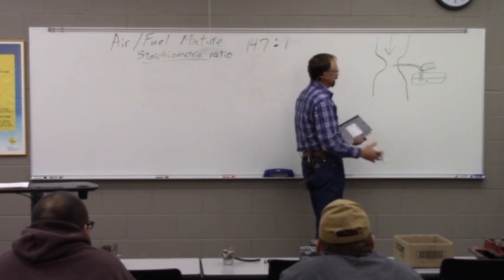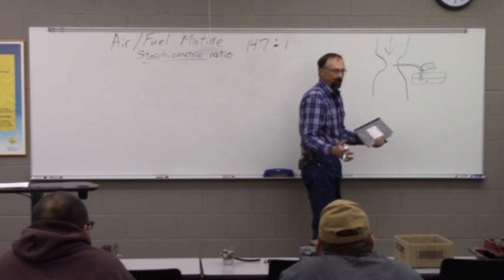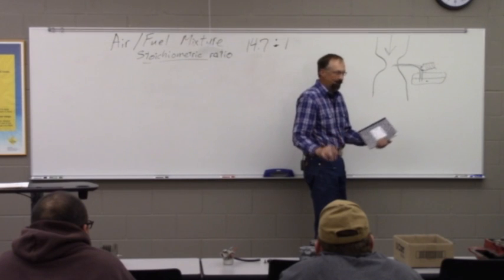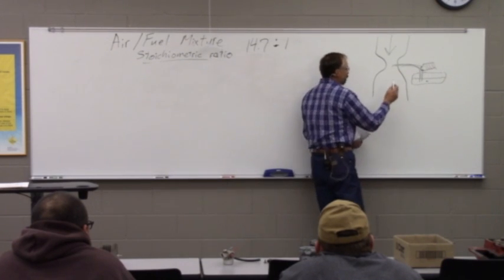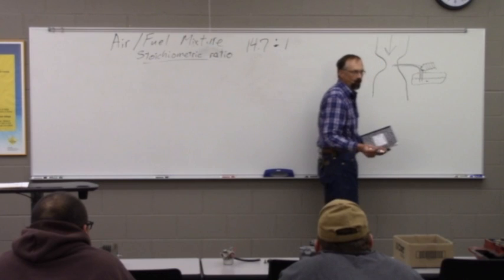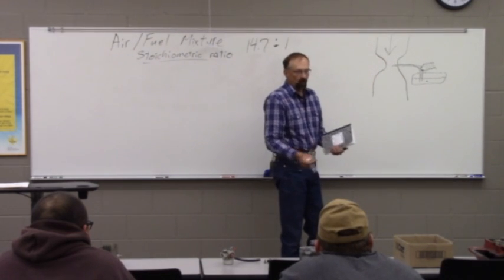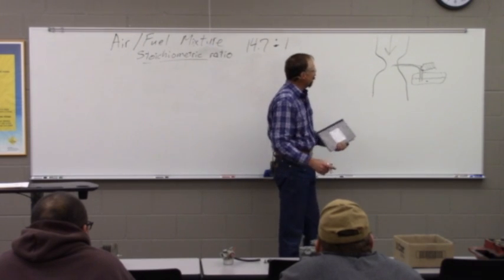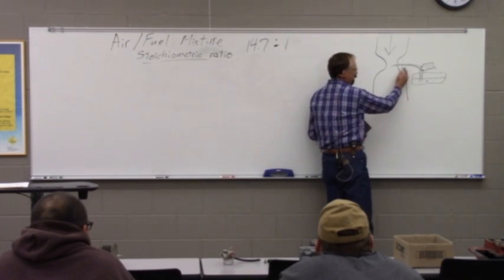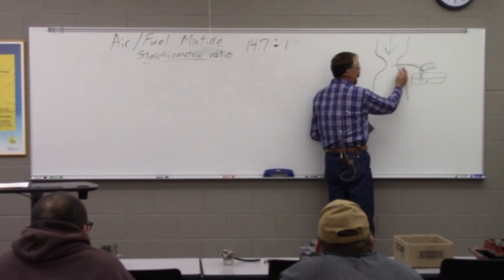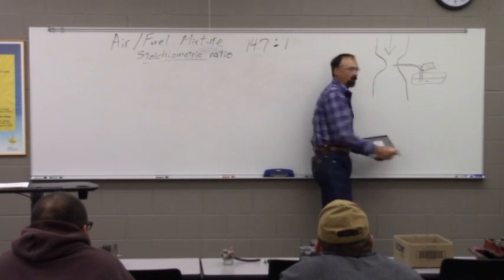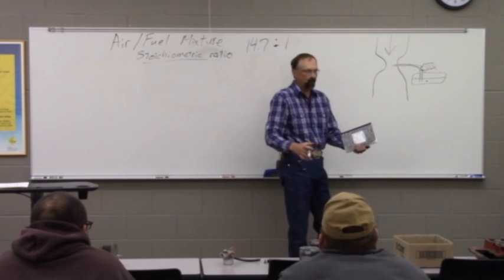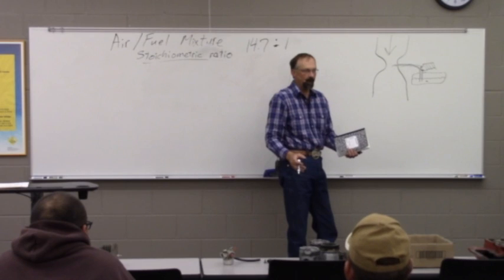Now, that's the basics of a carburetor. Now, we typically make all kinds of fancy side notes on that, and typically, most of the carburetors you'll find, whether they're on your lawnmower, your 1971 pickup, or whatever like that, are going to have one of these passages that's pretty small, that's designed with an adjustment for idle. So you can get that mixture right at idle, usually at 700 or 800 RPM, something like that.